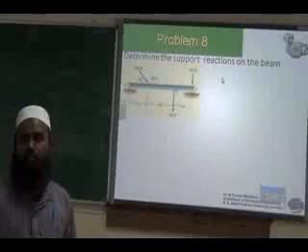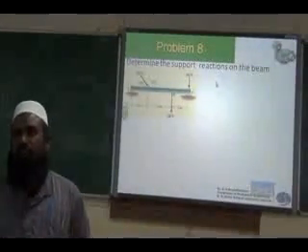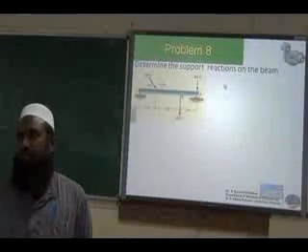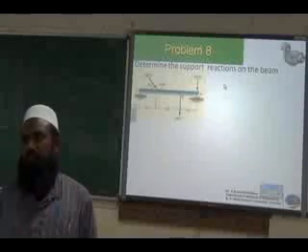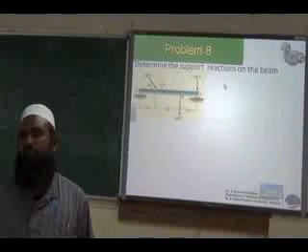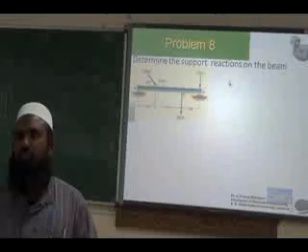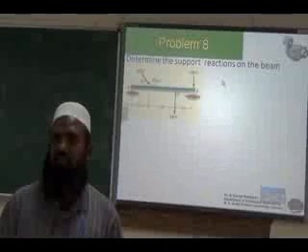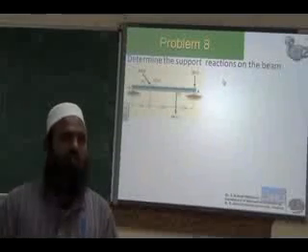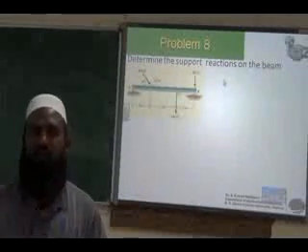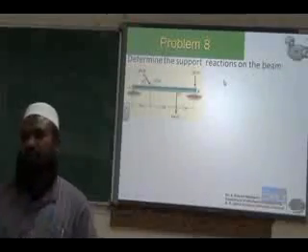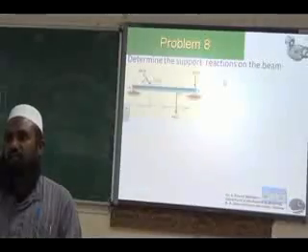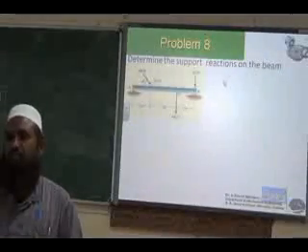Now we will see one example. We know what the equations are. We have applied them in our coplanar force system also. In particle equilibrium, we applied sigma F. In addition to sigma F, now we have sigma M, because a moment will exist only in a rigid body. A particle has no dimension, so all the forces on a particle are concurrent. We consider that the force system acting on a particle is concurrent. So there is no chance for a moment in a particle. A moment will exist only in rigid bodies.